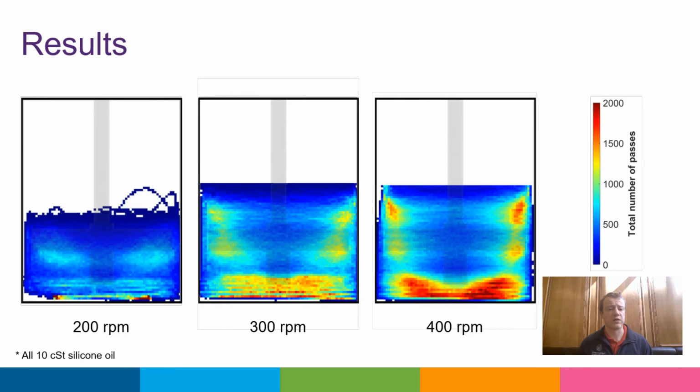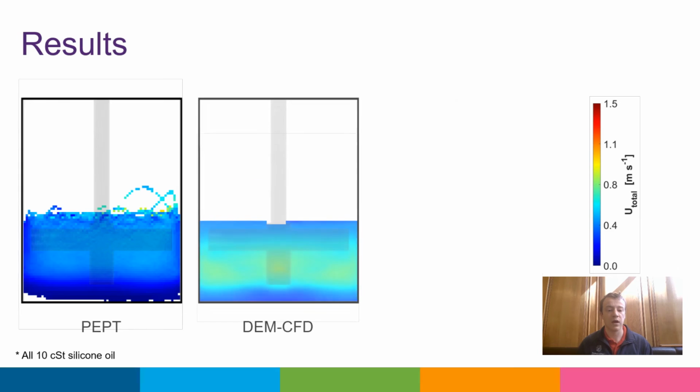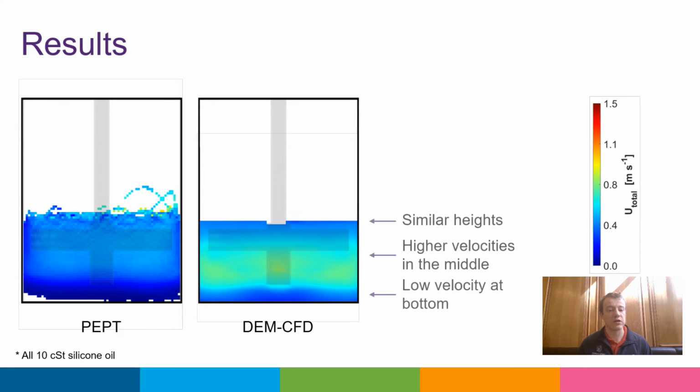These show that the media particles were able to reach the entire active milling space within the time period of each experiment, indicating that the system has good mixing. This is improved as rotational speeds increase, as more energy is being supplied to the mill, and the equivalent velocity profiles also show that the fastest motion is around the impeller tip, as this is again where the energy is greatest. Early simulations show that there is a level of agreement between virtual and reality, but there is potential to change the media and fluid parameters to further improve the level of agreement.